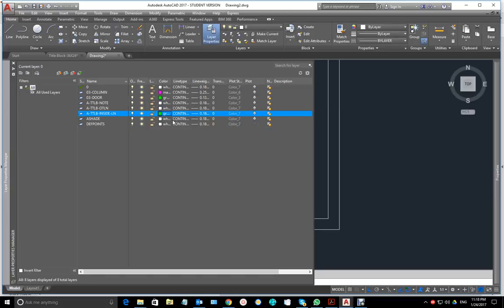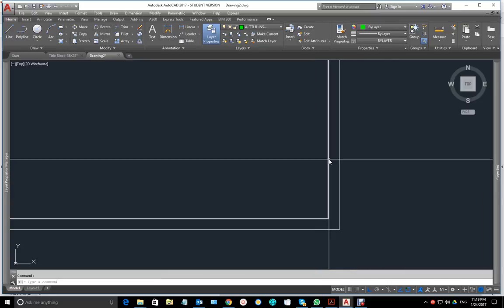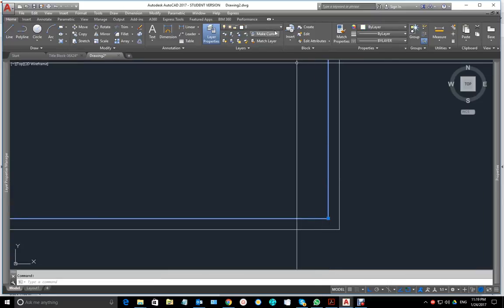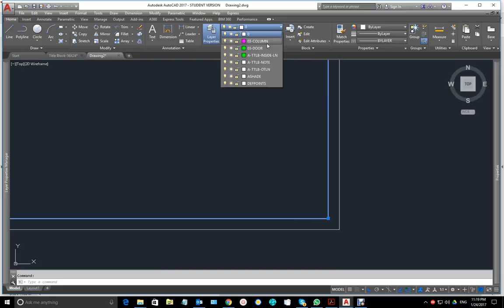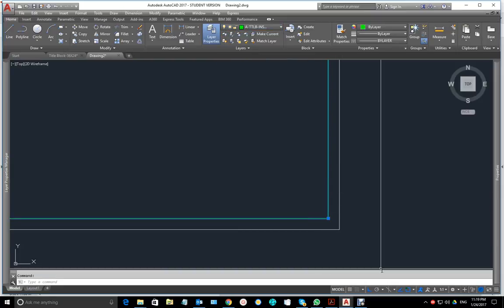The colors here are significant because, as the guidance I showed you before, each color should have a line weight. So don't worry about this now. We will discuss that later. So I will have this as a current layer by double click and then choose whatever I want to change, and then go here. I'll change it to the appropriate layer.